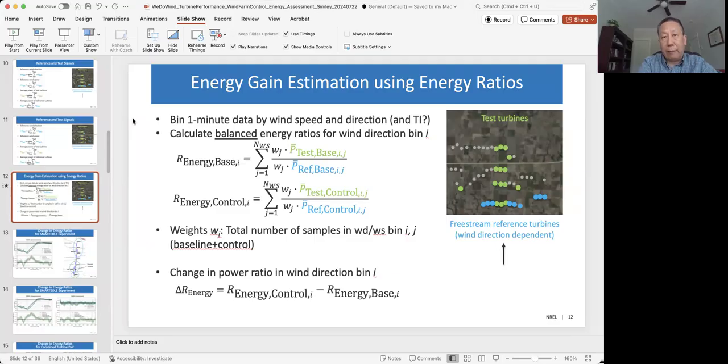Is that the mechanism you use? Even if the wind speed measurement is not exactly the free stream, even in the first front row, as long as they are in a consistent bias state, they can be used as a kind of reference calibration for the other turbines. Is that how you handle this issue, or do you separate the issue of wind speed correction from how you use the biased wind speed for the subsequent analysis? It's a very long question. Did I get my point across?